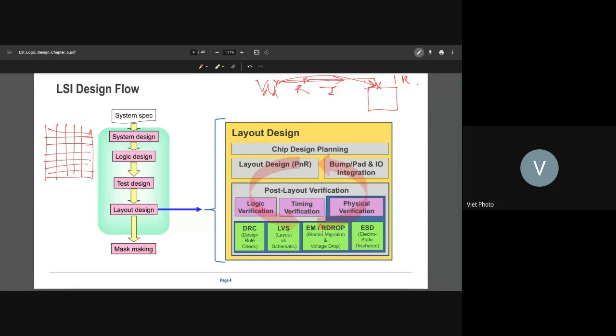You have that in almost every layer from the top layer down, so that it provides the power, the VDD, here. Because when you have metal, you have resistance, and when the current goes through resistance, you have the voltage drop. The voltage drop needs to be within a maximum of 5%, and in some high performance designs, they cannot allow more than 3%. It depends, but basically 5%.